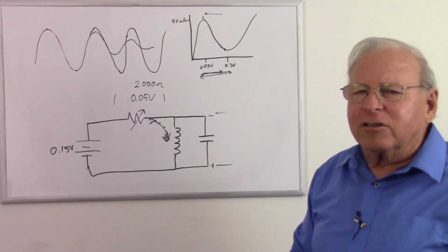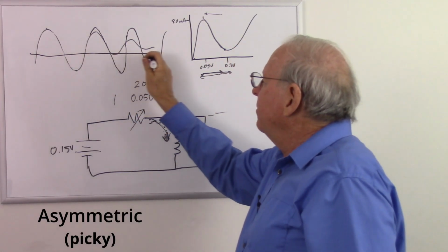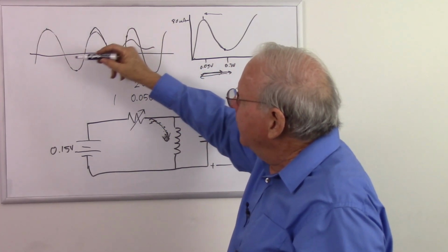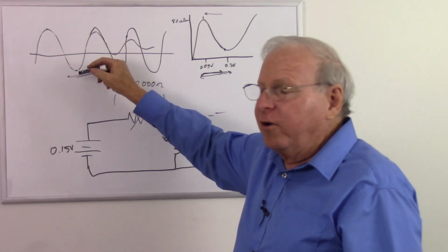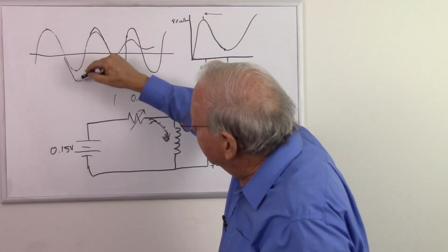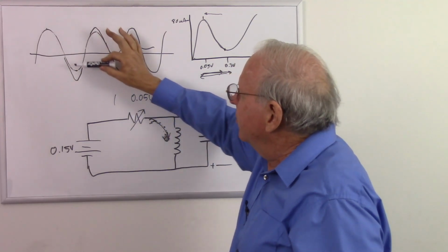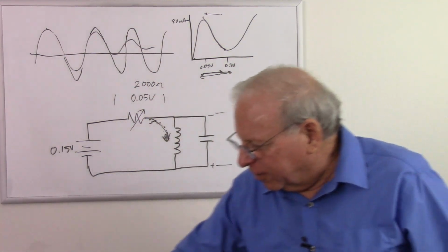And if you look at the voltage across one of these oscillators, you'll see it's a little asymmetrical, because we're not pushing this up, pushing that down, pushing that up, pushing that down. We're pushing that up, allowing that to go down, but we're still feeding some current into it, so it doesn't go down as far maybe as we'd like. But it just simply gives it an offset, so we get this nice sine wave oscillation. So that is how a sine wave tunnel diode oscillator works.